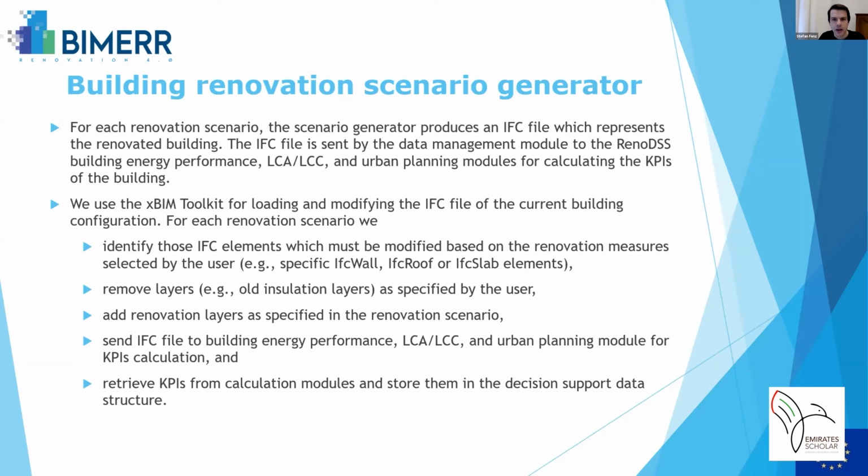What we are doing here for the IFC file manipulation is we are using the XBIM toolkit to load the IFC file and extract all the information out of it. What we are doing also with the generator is we are taking the baseline IFC file, modifying it in the system and providing the user a modified IFC file back, which represents also already the renovation measures. So you can take this file then and continue with the editing in Revit or ArchiCAD or any editor you like. So you're not trapped into our system.